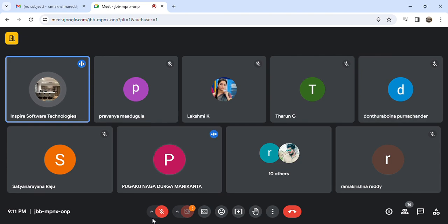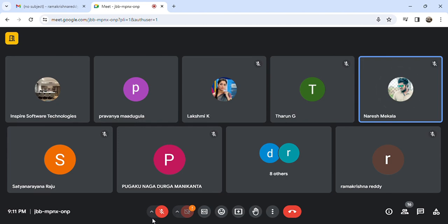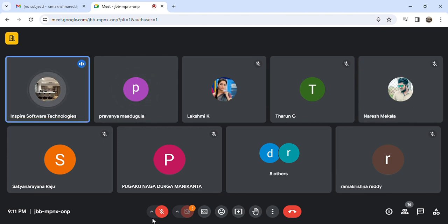Is CAN a synchronous protocol or an asynchronous protocol? Asynchronous. Why is CAN considered an asynchronous protocol? They don't have clock signals. Yeah, you have to say you don't have a clock signal. When you say that, then immediately the question comes: you are saying 1 Mbps speed, so how are you achieving the 1 Mbps? You need a clock, right, in order to achieve the 1 Mbps signal.